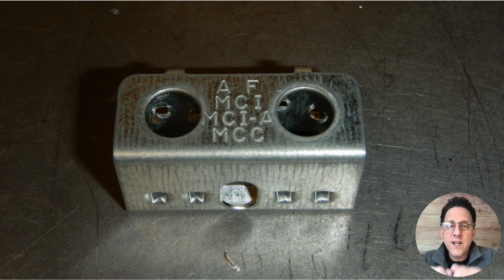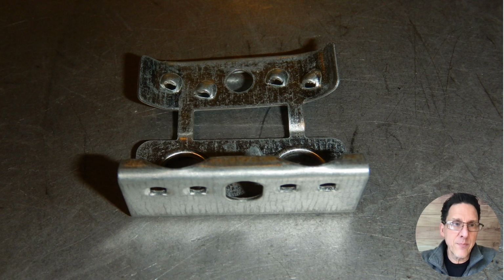All right, let's open the clamp up and see what it looks like on the inside. That's that clamp there. Now, by looking at it, you can probably guess it's not suitable for NM cable, right? Because if you were to tighten that down on an NM cable, those bumps there have a sharp edge. It's going to probably damage the cable. So don't use this with NM cable, right? Those bumps there are going to damage that NM cable.